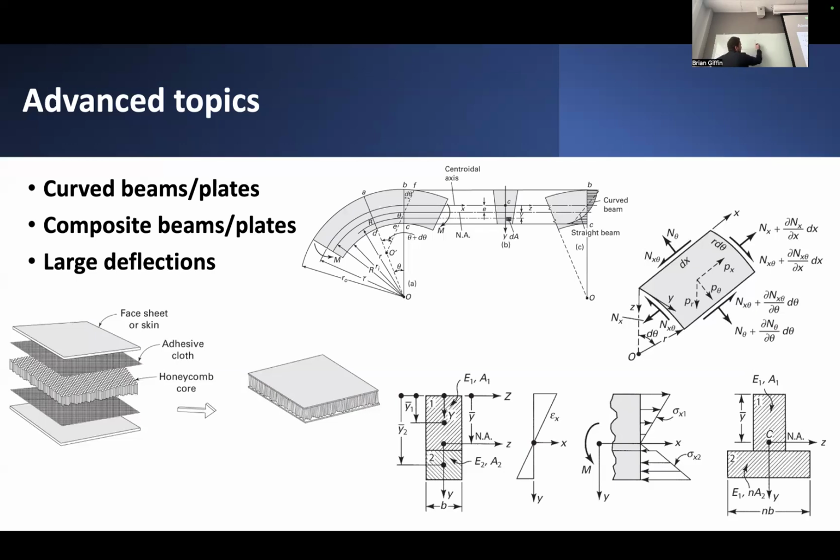In which case you might see that, if we're visualizing things like the axial displacement of this section under some kind of whole section rotation, within this inner core it might look like this, but then here it might taper off. So ultimately, you might have this assumption of planar sections remaining planar really being not valid if you have these relatively distinct distributions between stiff material and soft material in a layered composite.